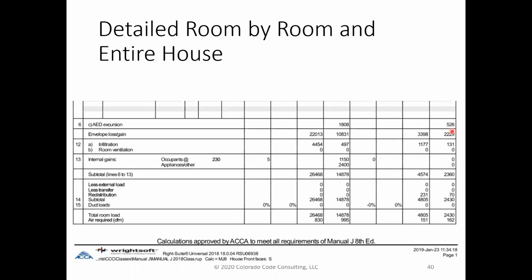To a designer, when you start hitting thousands of BTU, like I said, there's rooms with a solid wall of glass facing west. That number there would be 12,000 BTU. That's a ton of air conditioning. That's the excursion, and it only gets that hot for that amount of time during the day, right?